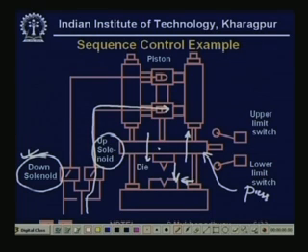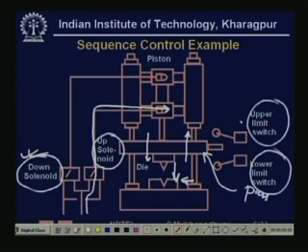And obviously what happens is that it goes up, the up solenoid may be de-energized. So, whether it has reached the topmost position or the downmost position, this needs to be sensed. So, there are two sensors. This is the upper limit switch and lower limit switch, and these are the two actuators. The down solenoid and the up solenoid are the actuators, and this thing is our system.